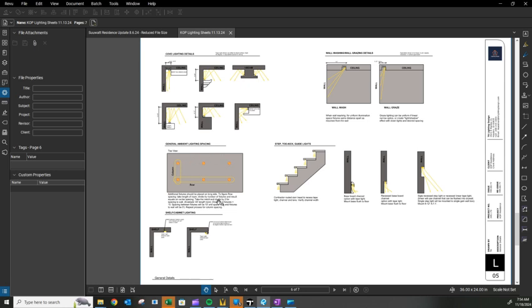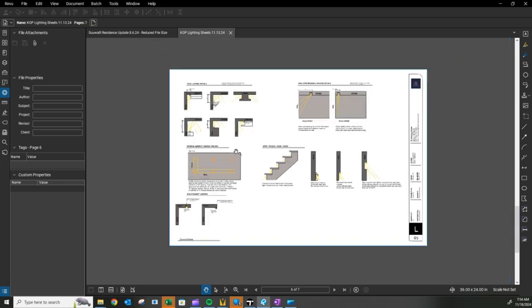The mathematical way to place it out, you take the length, divide it by the number of fixtures, and that's how far out you space your fixtures, and then half of that to the wall, because there's no other light over here, so that's why you do half. And then you also look on the fixture to see the spacing criteria, to see if it can handle being 8 foot space apart without creating light gaps.